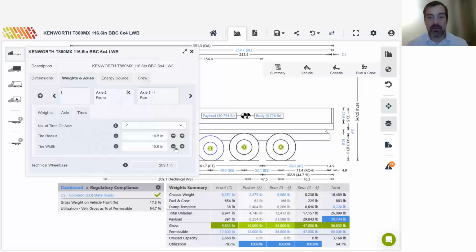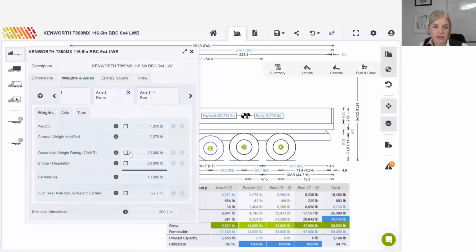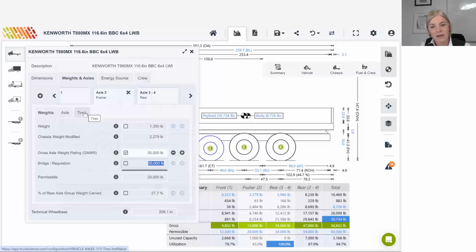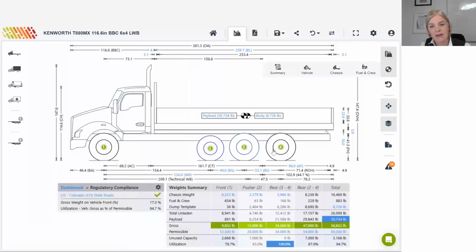I think you might be limited by the manufacturer's specified weight for that pusher axle there. Okay. The gross axle weight rating of 13. Do I push that up to about what, Paul? Help me out. Oh, you can push it up to 20, I suppose, but I think that in this case, you're not going to be limited by the tire weight, it looks like. Okay. It's not going to have an impact there. Okay, in this case now, the tandem axle is maxed out at 100.